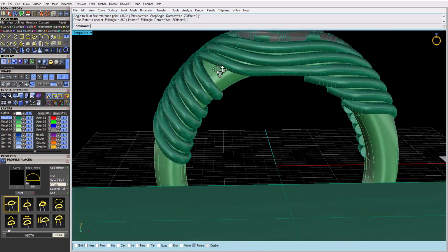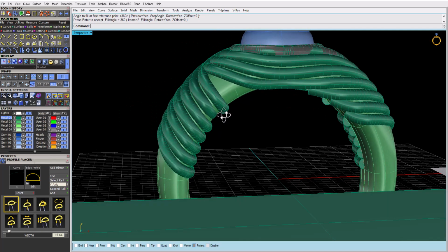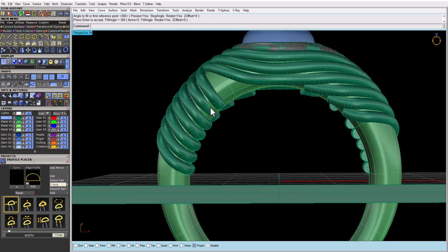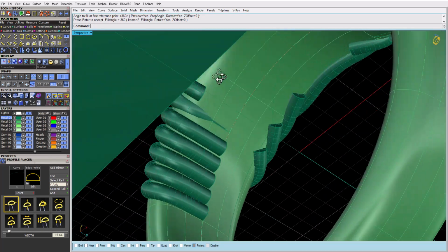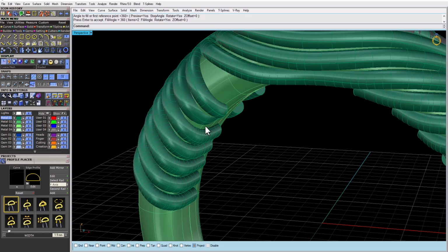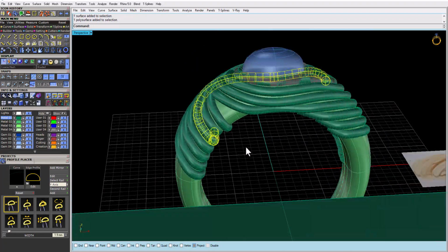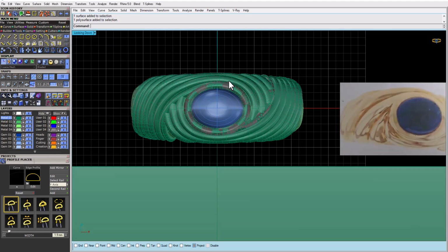Yeah, and I would just offset this, and in the end I would just follow the same thing which I've just shown here, with this one over here. Just scale them inside and we are good. Okay, I'm not doing it for the complete pipe, but you just have to follow the same procedure. There's nothing difficult. So that's it, guys. Instead of pipe, you can do a sweep one, add a profile.